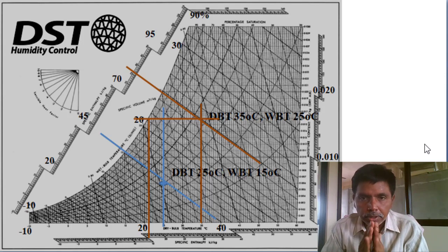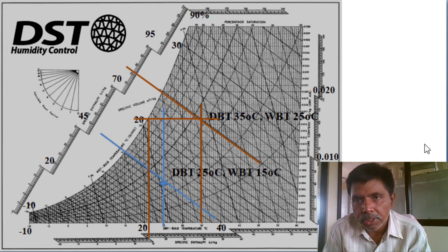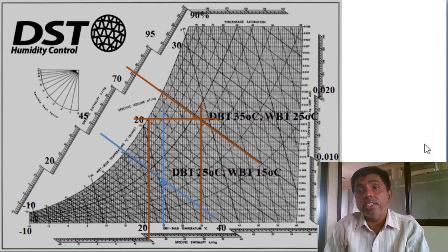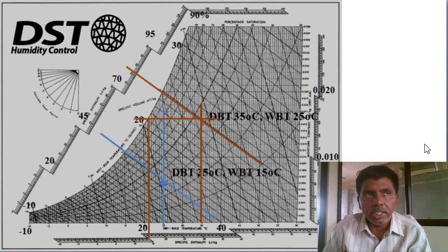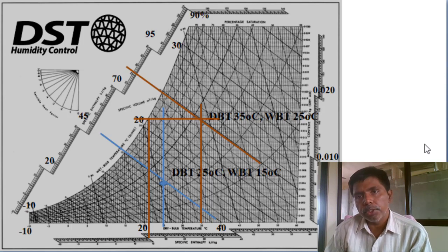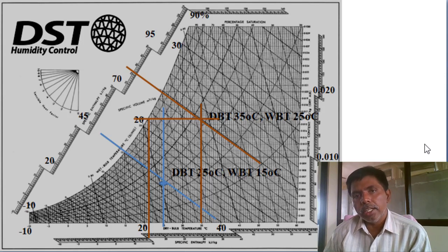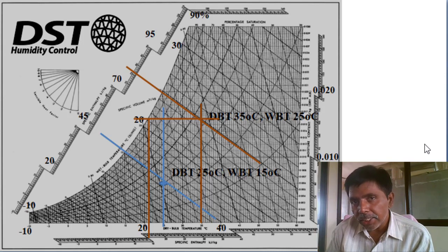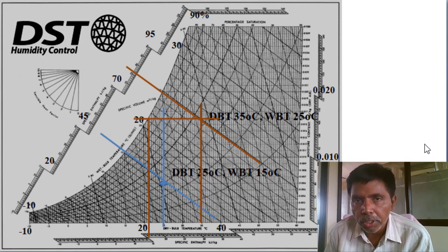So these are simple problems. In this unit, we discussed how to extract the psychrometric properties, and how many methods there are for an air conditioning system to achieve human comfort. What are the human comfort targets? One, continuously remove the generated heat, which means maintain and control the temperature, not decrease or increase. Second, control the humidity in the air, with relative humidity in the range of 40 to 60 percentage. Based on the human being working, the rate of heat rejection changes. Based on the rate of heat rejection, the flow rate of the air is important. The volumetric flow rate of the air is important.